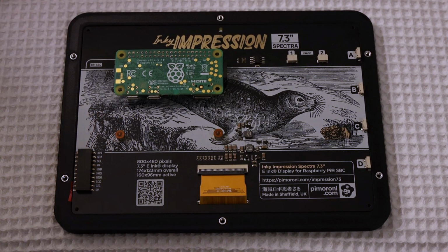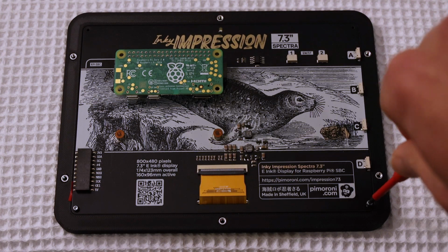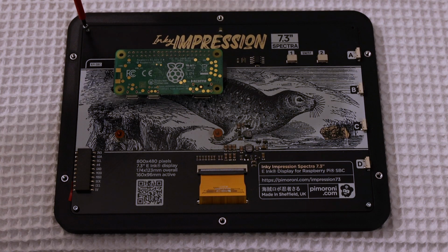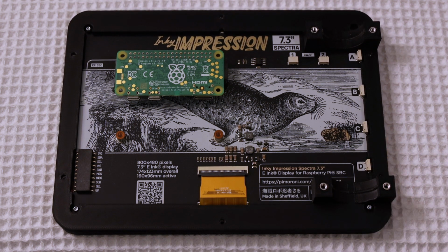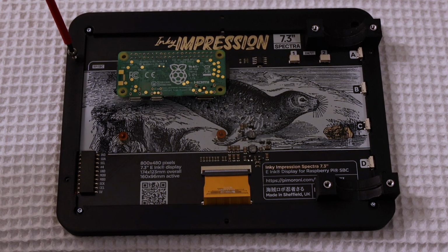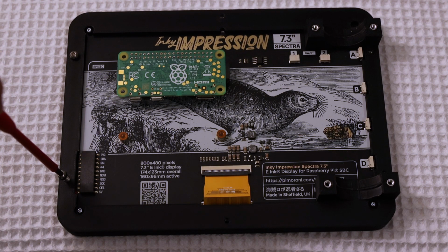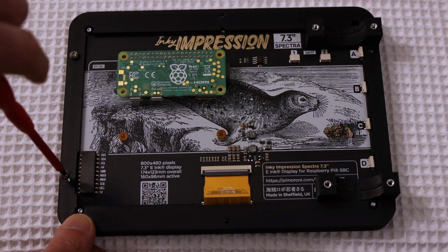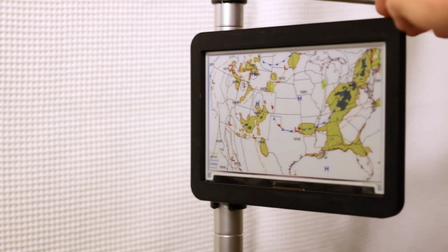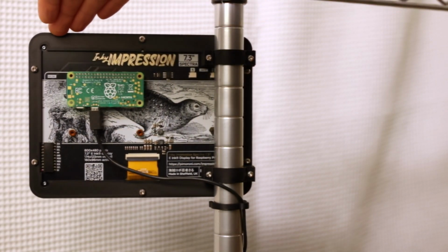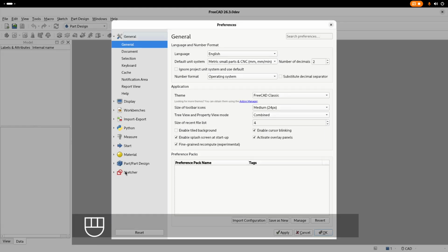The e-ink display board is recessed into the front frame element and secured with M2 fasteners into threaded heat-set inserts. The rear frame element further secures the circuit board in place and provides half of the post clamp. The rear frame element is secured to the front with M3 fasteners into threaded heat-set inserts. Pipe clamps secure the rear frame element to the 1-inch post with M3 fasteners into heat-set inserts installed into the rear frame element. To model this frame in FreeCAD 26.3, first edit Preferences and enable Sketcher Preference.